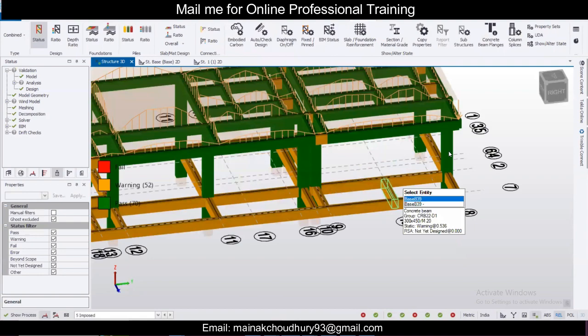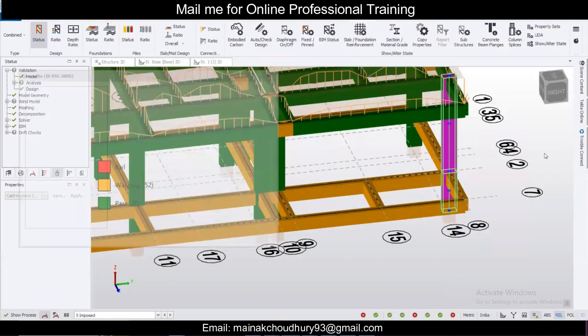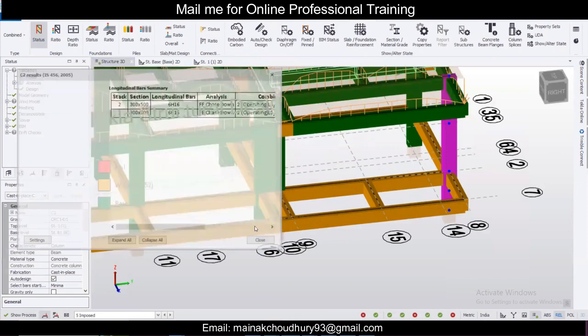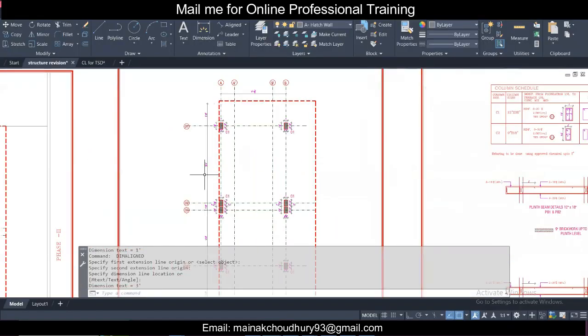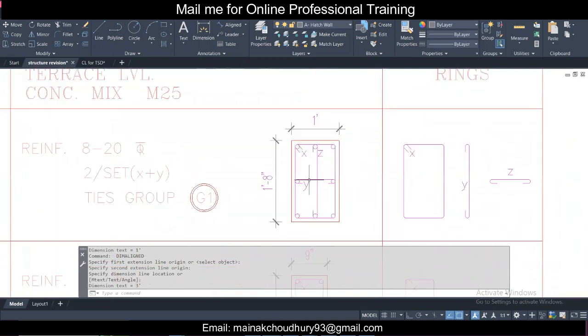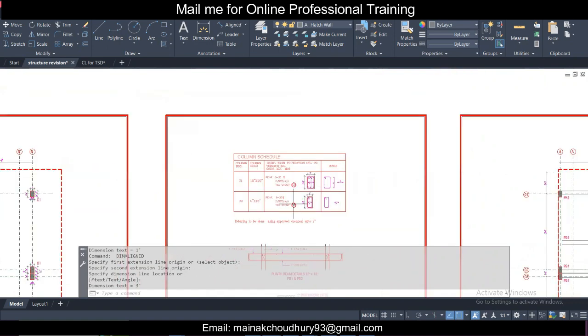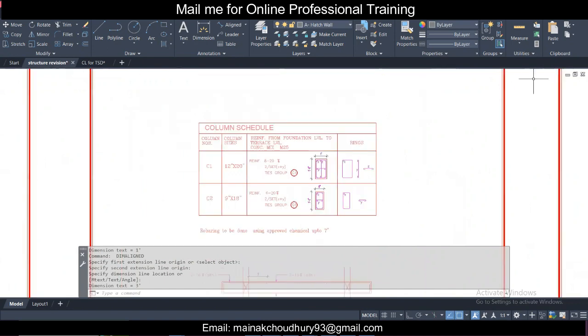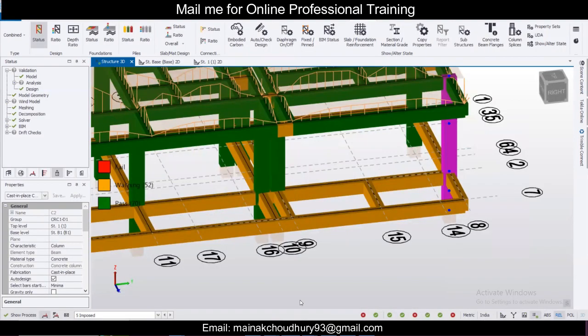Yes, so column reinforcement, first of all, let me check here very quick. 6 bar of 16, and what we have provided in this column is 8 bar of 20. Okay, this, by the way, is not considering earthquake load, not even considered here.